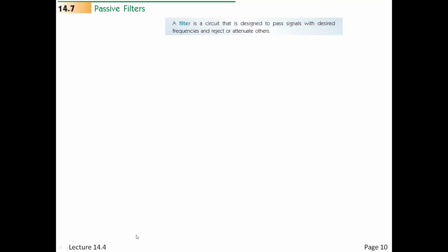So we can make filters of several types. I mean, when you think of the basic question, is a frequency present or not? So we have yes and no, and how are the ways we can combine that? Well, the first would be we could do a low-pass filter, which says, just as the picture shows, there's a pass band, some cutoff frequency, and a stop band.